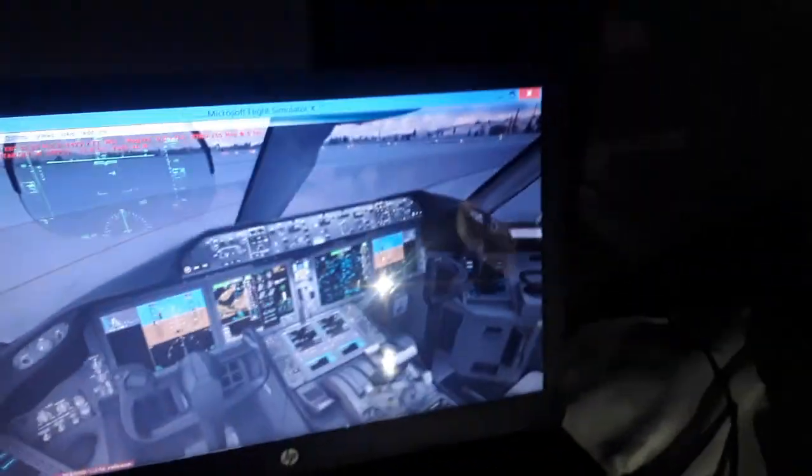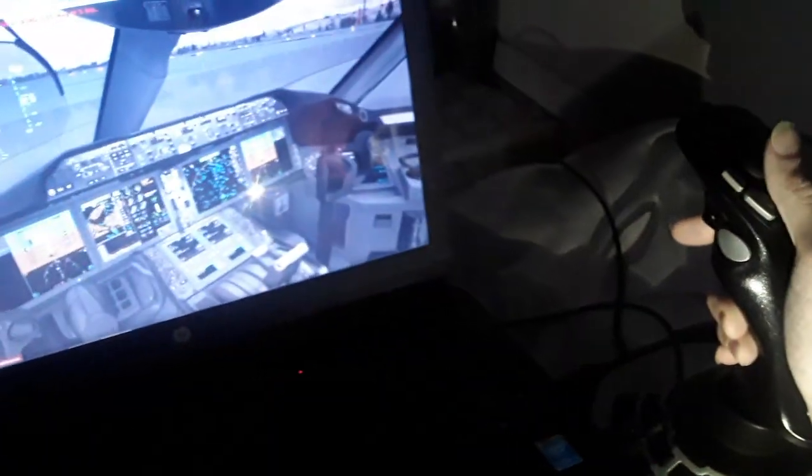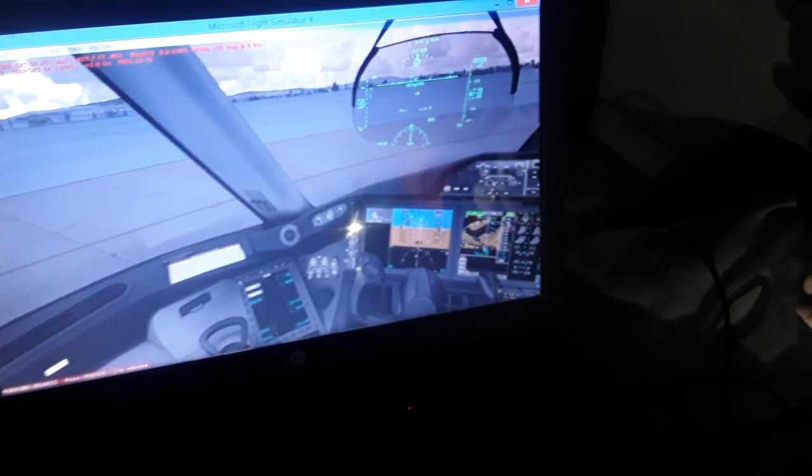We're gonna have the flaps extended to like 35-30 degrees. The landing gear extended and pitch attitude to like 9 degrees for approach and landing, and an airspeed of about 160 knots. So you will see all these things. We will be flying the flight controls also manually over here, as you're gonna see, for approach and landing.